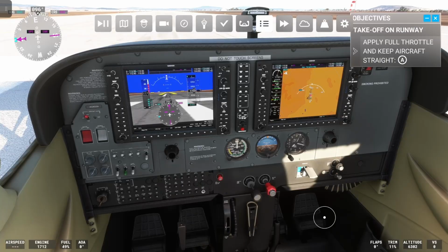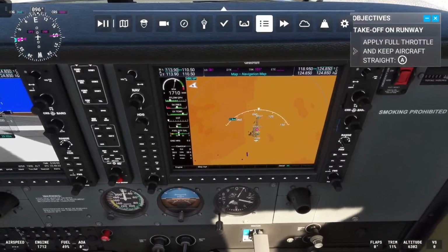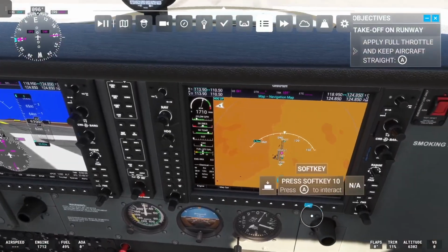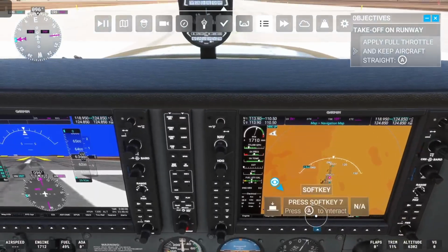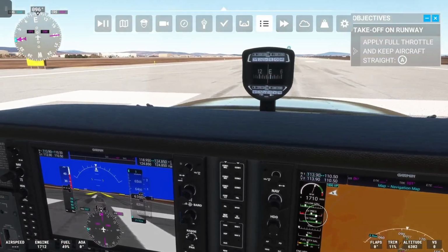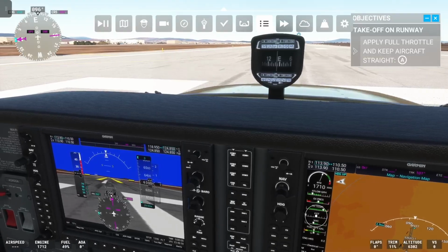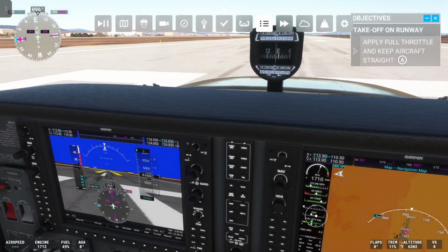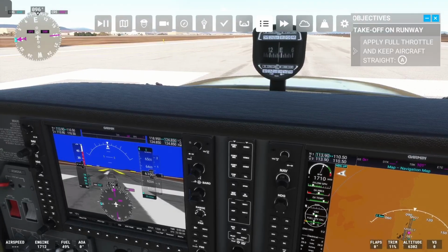So we are on the instruments in green phase. Let's see if instruments are green under these conditions at 1700 RPM and everything else adjusted. So we want to check oil pressure under 1700 RPM. It is green. Oil temperature is green. And the ammeter, it's charging, I assume. That's usually how it goes. It's 0 and eventually it shifts.